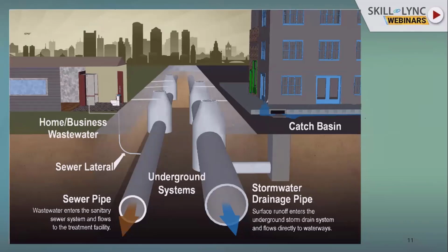Because in the city, the space is very limited. You don't have space, so nobody will allow you to make big channels along the side of the road. No municipality, no government will accept this. What they will say is, we don't have space. Space is very costly in urban cities. So that's why in most urban drainage systems you will see pipes with manholes and catch basins. This we design mostly in the urban city because there is a shortage of space and the space is very costly.